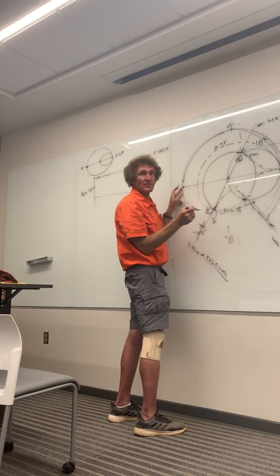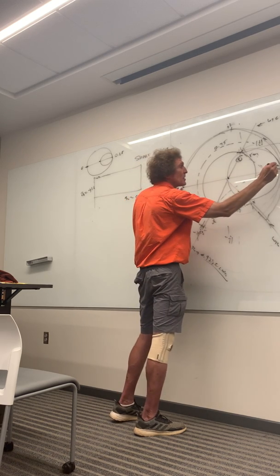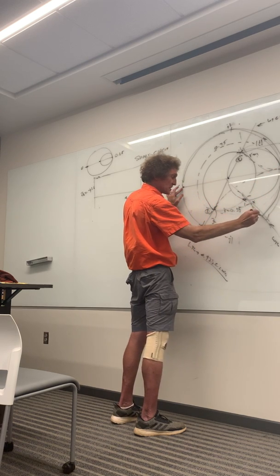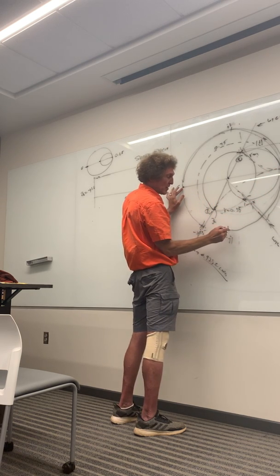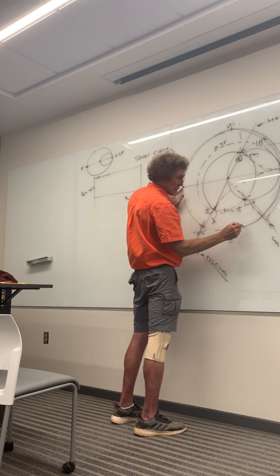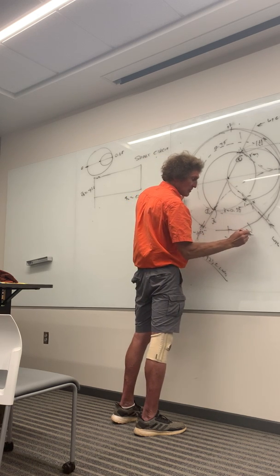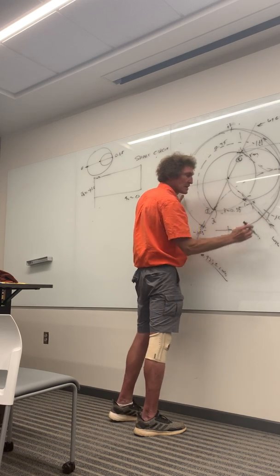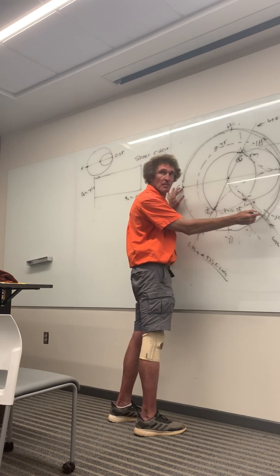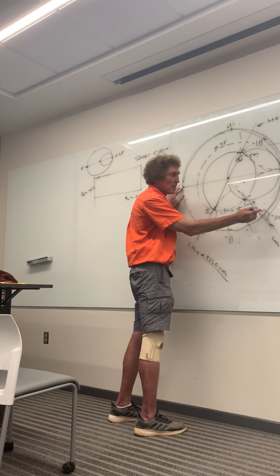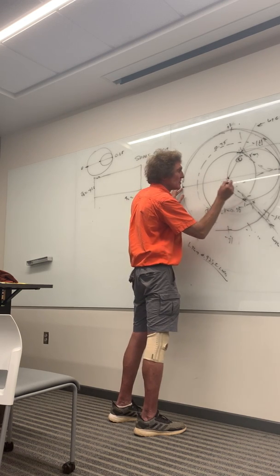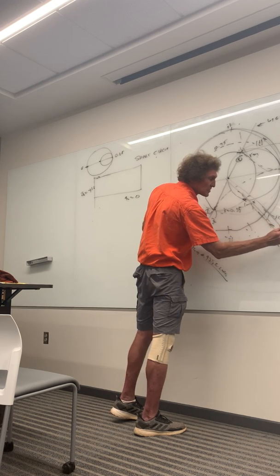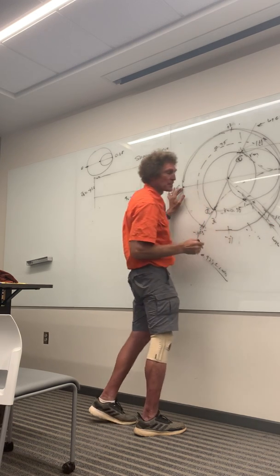I keep going down here. That's a full quarter wavelength, right? And then I keep going down and I need 1.6, so I'm going to go minus 1.6. So I go through to about where? Here, is that minus j1.6 or about here, isn't it? Minus j1.6. Take a look at that outer rim. Yeah, it's somewhere around there, right there. All right, so now how far did I go? We'll just take a look. Draw a straight line through there. And what is the wavelengths towards generator here equal to?